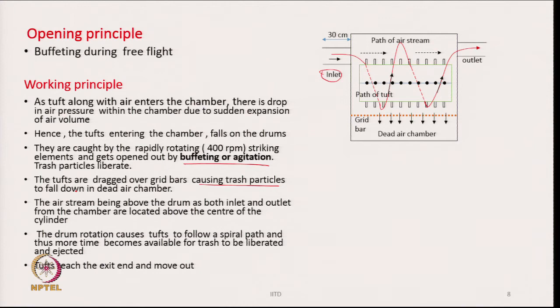The airstream is above the drum, as both inlet and outlet of the chamber are located above the center of the drum. If you look at this, the inlet is here, the outlet is here, only very light and smaller tufts may follow a straight path and go from inlet to outlet. It may happen with some tufts, but the majority of the tufts, which are heavier and larger, will be falling down.